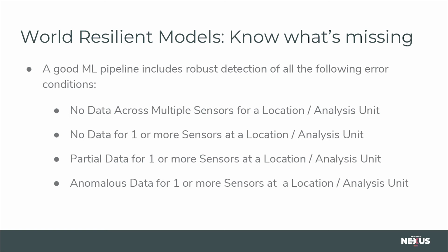On the other hand, if we've got 30 sensors at a location, but one or more of them aren't giving data, but the others are, that tells us that we still have basic communication, we have the power in place, we have the routing in place, but we're having problems at one sensor, usually one sensor. Sometimes it's more than one sensor. Sometimes sensors are on what's called a run, which is a single cable line. If you see that, for instance, 5 or 6 sensors are down, one thing we'd always want to check is, are they on the same run? Which means that there's a problem just with that cable run. Everything else might be up and working.